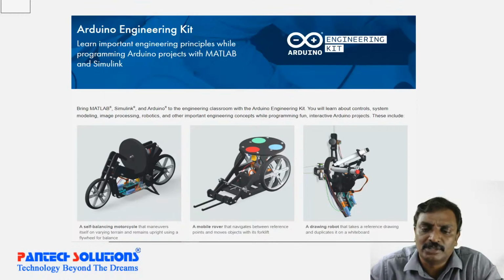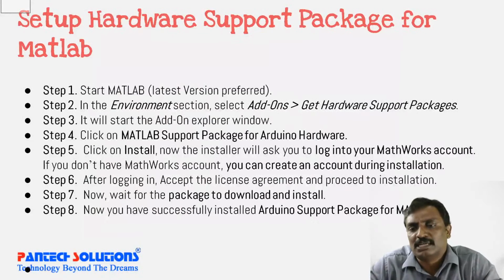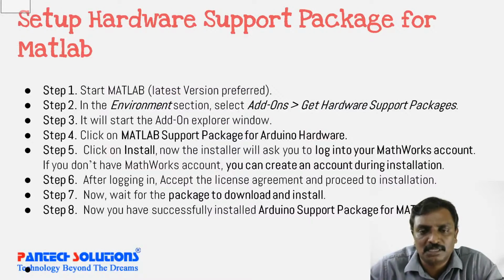So these are based on algorithms. It allows you to implement complex algorithms on Arduino, which is quite tough when you go with writing the code in the Arduino IDE. To set up Arduino, the first thing is to install the hardware support package for MATLAB. I told you that it has two options: either you could go with the Simulink option, or you could go with the MATLAB option.